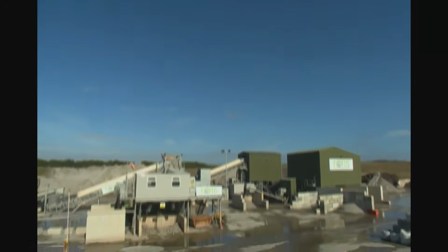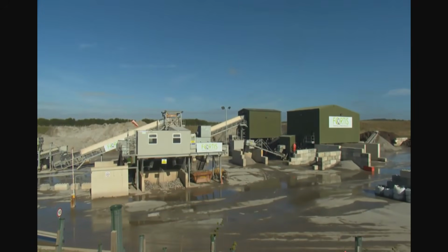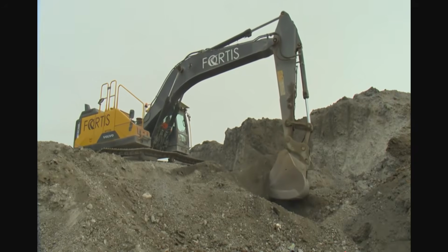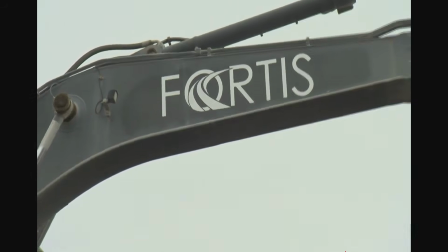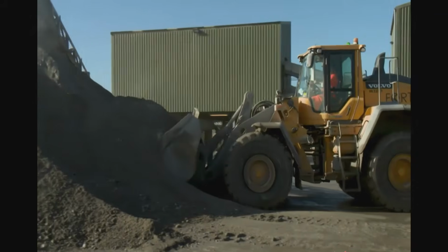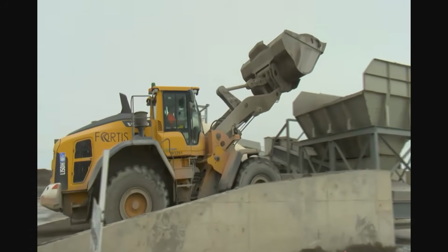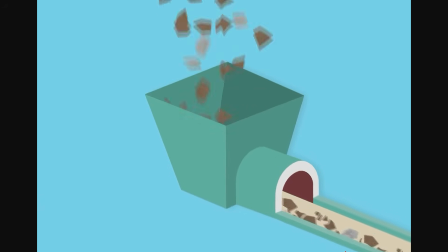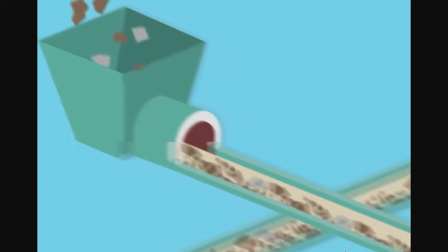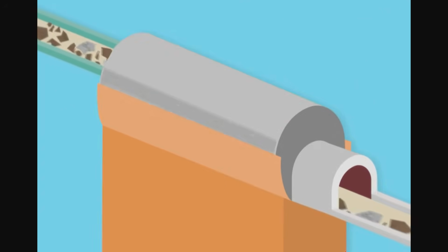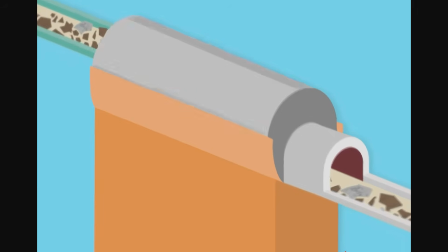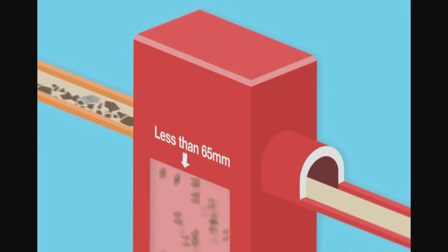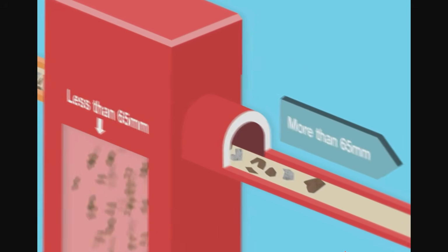Fortis is known as a leader in the recycling, processing and distribution of IBA for use as a secondary aggregate in construction to build developments. So the major objective of using this bottom ash is aggregate purposes. The government of Jersey has worked with them since. So this is the feeding for the separation process, you can see here, into a hopper and through a series of conveyors into a rotating screen that separates the material. These are the different screens, and you can see the different target sizes. 65 millimeters passes through the screens, so less than 65 mm is getting separated, and the more than 65 mm.